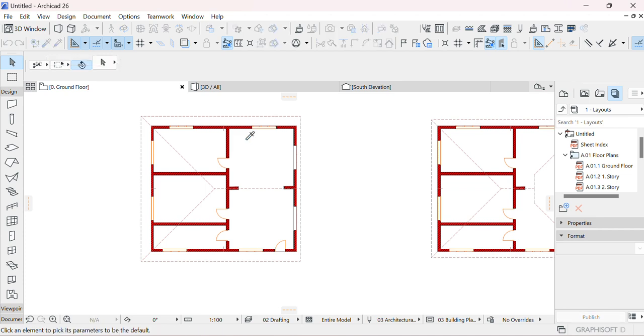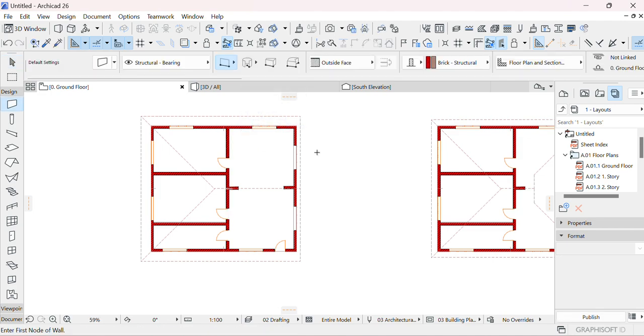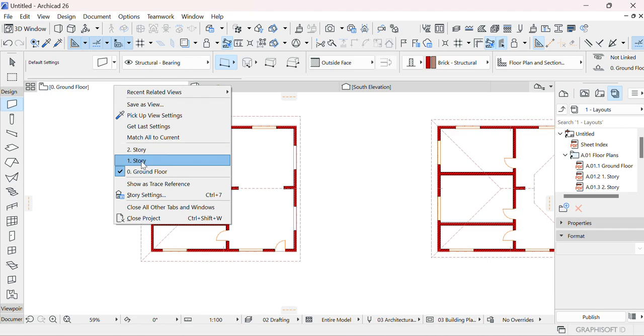So I click that, then I pick the parameters here. Now can you see it's like I've already instructed the computer to start drawing walls by just picking those parameters. And I can inject these parameters by picking that and injecting them on a certain surface that might have different parameters. So I go on first floor.